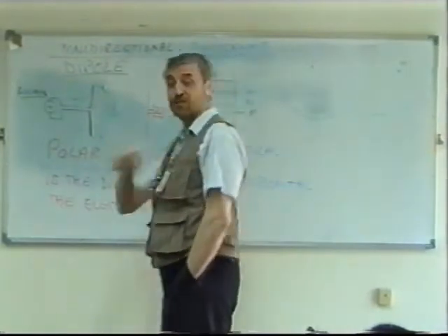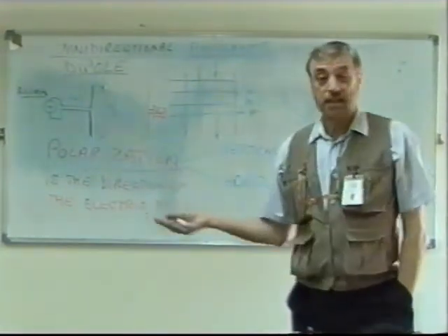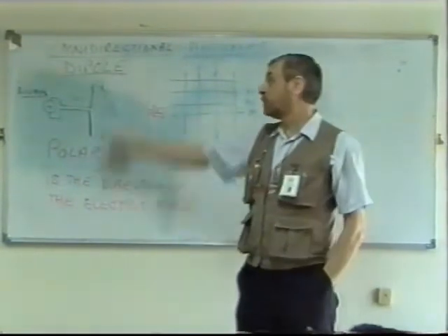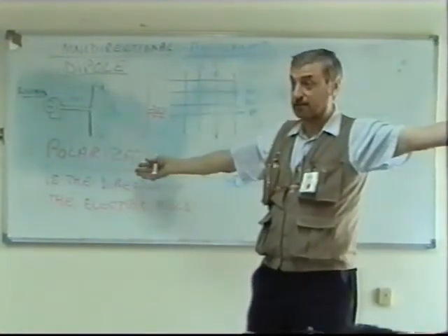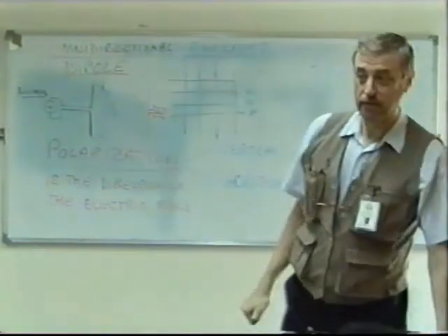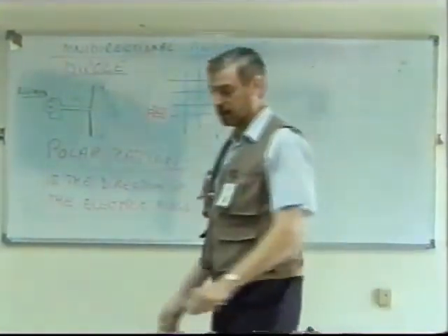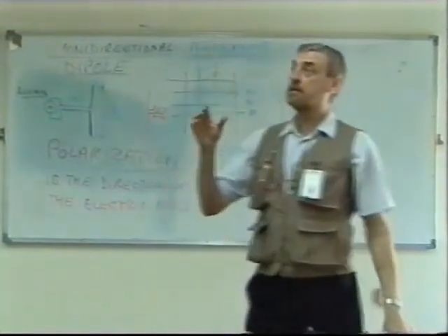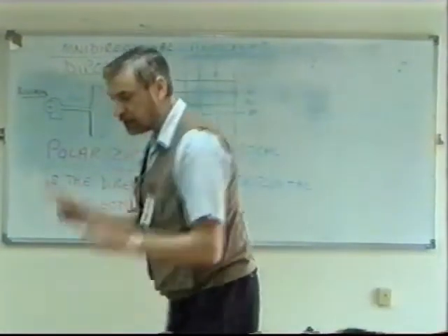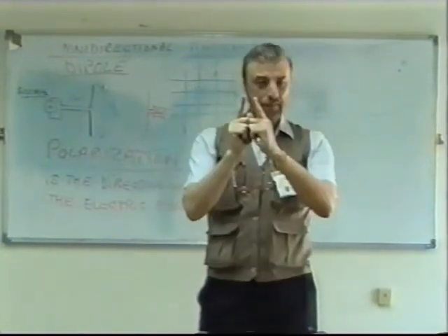Theoretically, a dipole can be used at any frequency. The only limit is practical, isn't it? That's all. Space. I mean, if we were talking about very low frequencies, that dipole would have to be hundreds of kilometers long. In theory, yes, but in practice, not something you would do. That's the only difference. So really, we've got to think of the practical aspects of the dipole. But if we're talking about, say, microwaves or UHF, then the antennas become reasonable. A dipole's only that big, or maybe only that big.